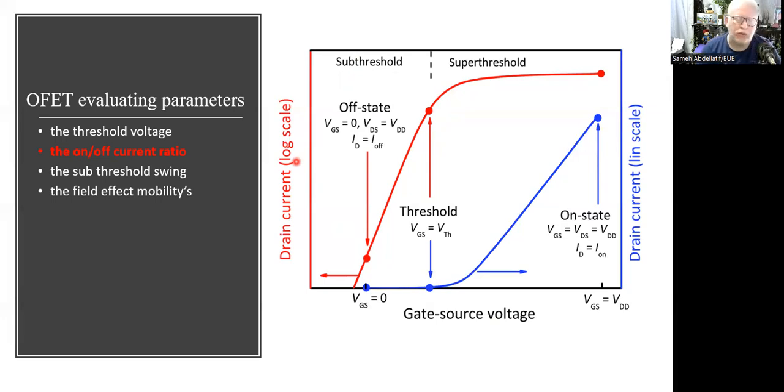Why is this important? This is simply because when we start doing power management or energy management for our circuit, we simply assume that when your transistor is off, I mean the voltage is below the threshold voltage, your transistor consumes zero power. But practically this is not correct, because as you can see in this red curve, you still have some current.